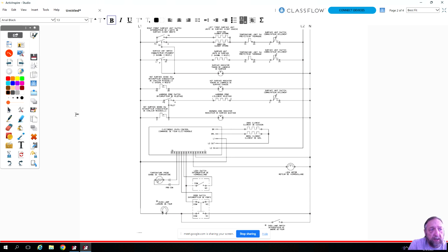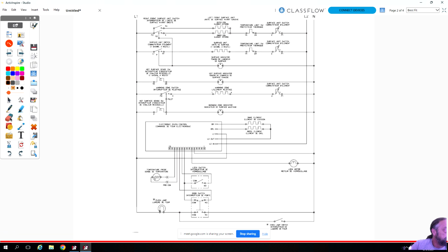circuit. Let's say a customer calls you out and said the oven does not work. So the first thing is, what is the load that we should be looking for in this wiring diagram? I'm telling you that nothing works in the oven. You said in the oven, it works, but it's just not in the oven, or is the whole unit not working? No, the stove's working, the cooktops are working. Everything's working up top. All the indicator lights, all the elements, everything's working fine. We go there and our oven control board's not even lighting up.